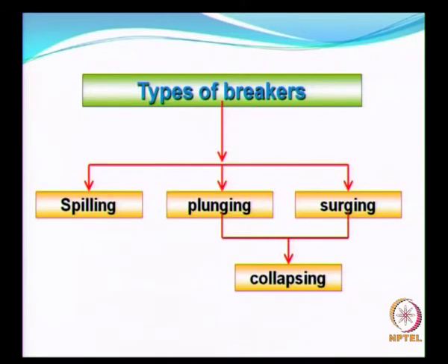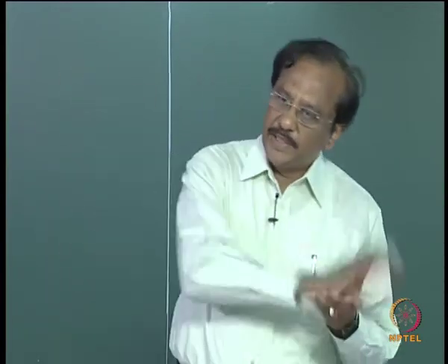Now we will move on to types of breakers. When we look into types of breakers, why is it important? Why are we studying about breaking of waves? From a structural point of view, when you have a structure and the waves come and hit the structure, the force exerted is an impact force.